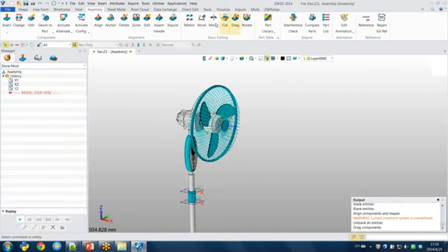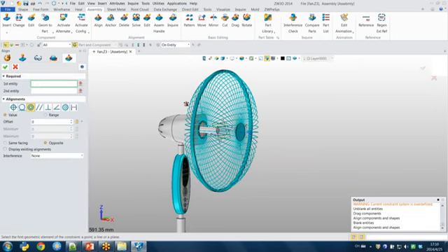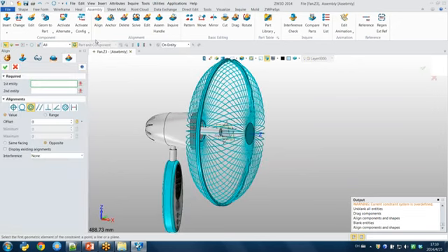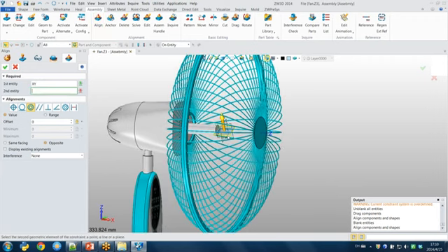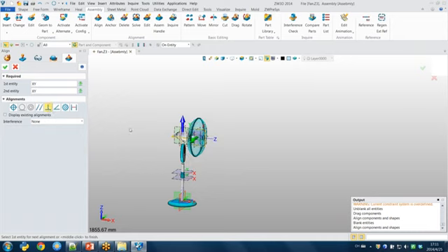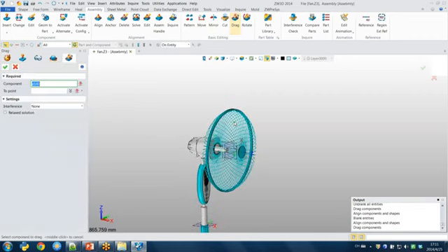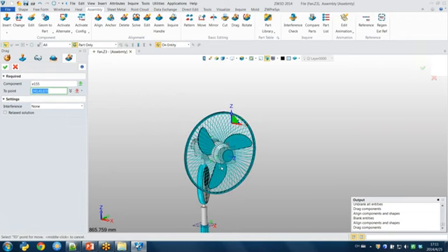So I also need to set the alignment. I can blank this one first. So align this frame, they are constant, or you can also set them as perpendicular. Doesn't matter. Okay. Press OK. So after you make it, you can find you cannot drag it again anymore. Okay, you cannot rotate.